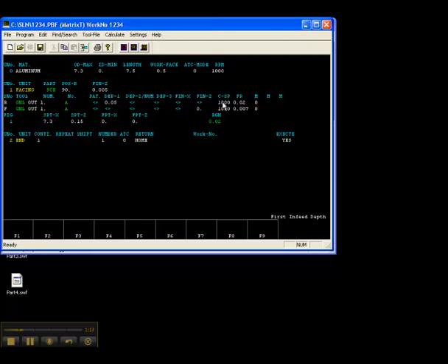On the right side here we've got the spindle speed. That's from the tool info window. And the roughing feed rate, that's again from the cut info window. Because in the cut info we told it to do a quote-unquote cleanup pass, it developed a finishing tool as well. The finisher is just a copy of the rougher. So if you wanted a different tool, you'd have to edit it right here in our editor.